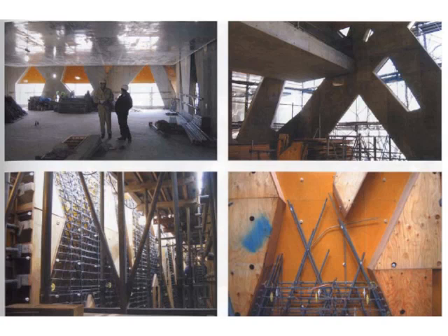And you can see as they're building it up, here's another example of that formwork. This is obviously where that Y is going to go. These are the voids where the windows are going to go, and we're tying that formwork into place. So in order to pour this concrete and have it not have air gaps in and around the density of this material, they had to use that very special concrete that was called self-consolidating concrete.